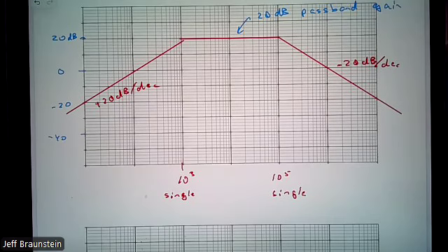-6 correction because I have a double pole. And I have no longer met spec because my cutoff frequency is not 10 to the 3 and 10 to the 5, because my correction is -6. So what do we do instead? What do we build to give us our 40? A second order circuit. And what sort of second order circuit is going to give us this part?